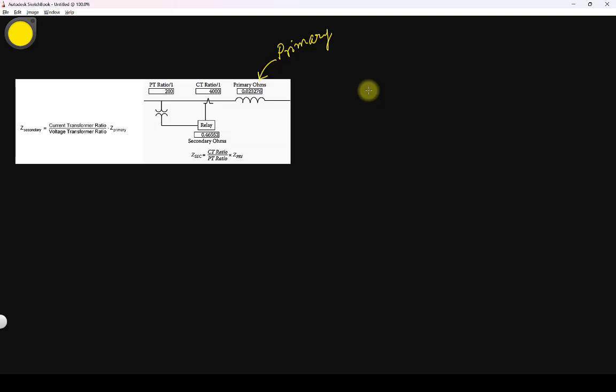For example, if you have a transmission line, we have three conductors, for example. If you connect an ohm meter and calculate the resistance R, and also you measure the reactance jX. So in short, using the equipment, you are measuring the impedance of the line directly using some secondary equipment. So you are measuring the R, X, and ultimately Z by using the measuring equipment.